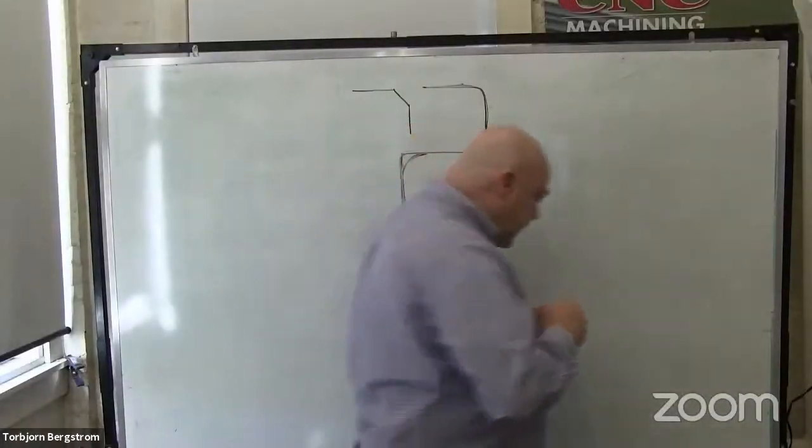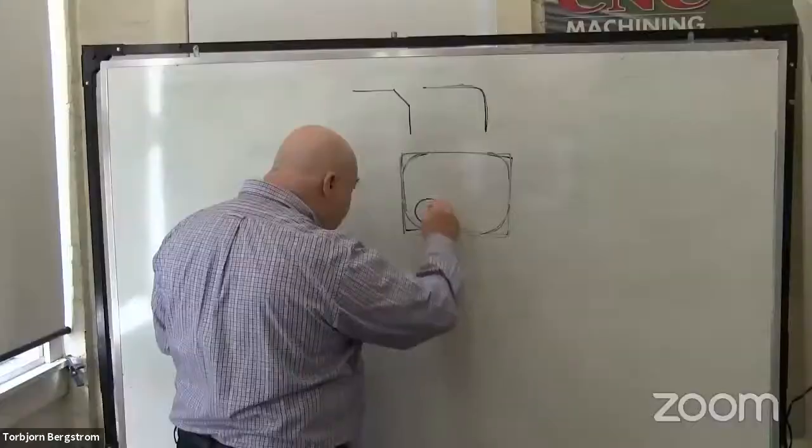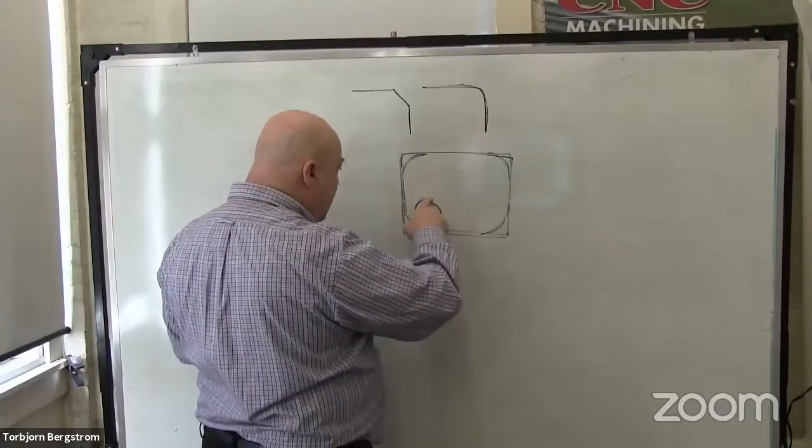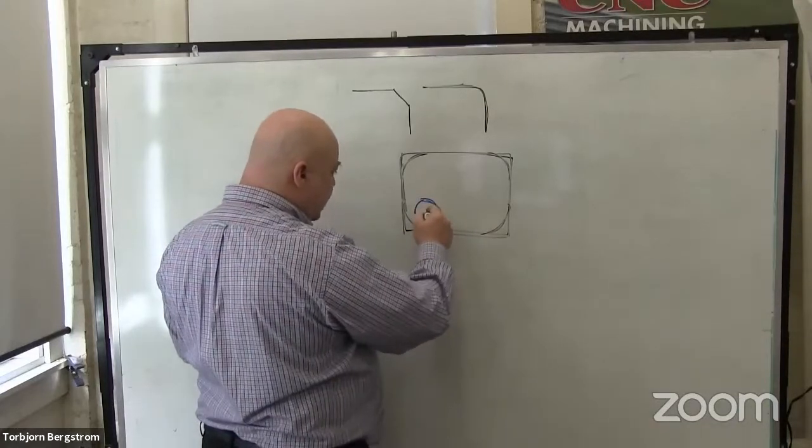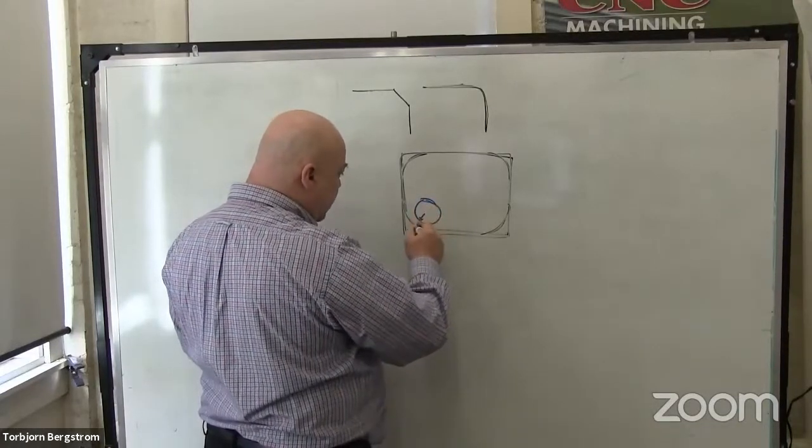And we got to the point with the corner radius where your tolerance is like half the diameter of the tool. So whatever our tool diameter is, we want half the diameter of the tool, the radius in this direction, to be smaller than this radius.